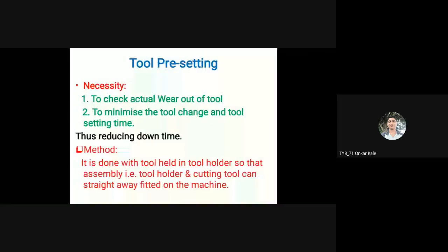So you just take care in terms of the tool setting, then to minimize the tool change and tool setting time, you ensure that once you install that tool into the system, you set up that tool. So whatever the operation time for that particular tool, the setting time for that tool and ultimately the time for the tool change, you have to do this calculation before the manufacturing.